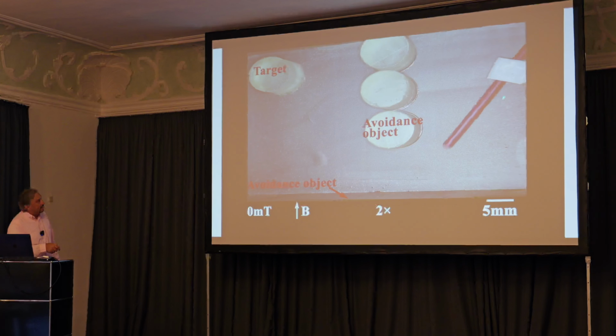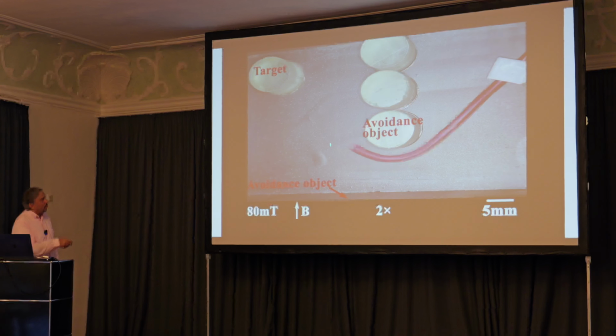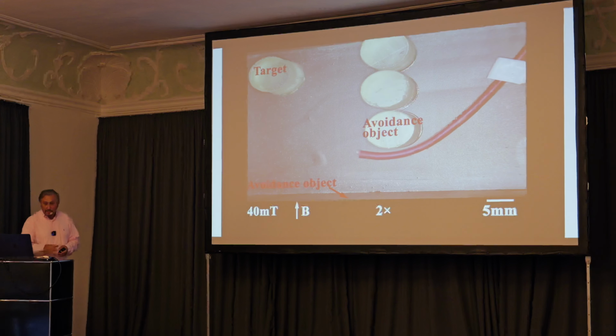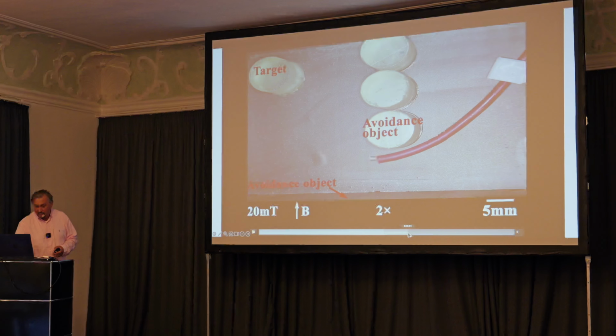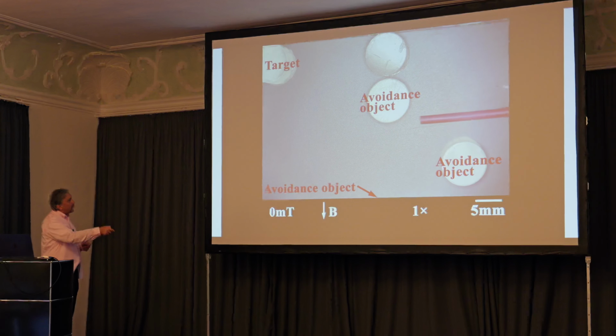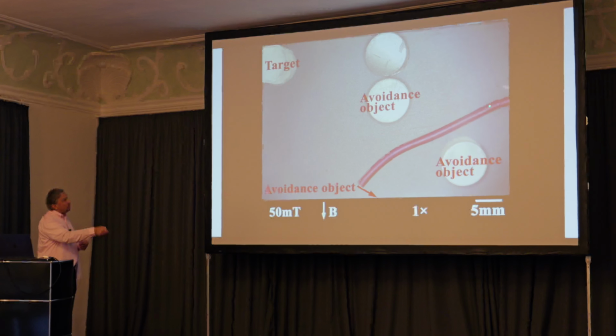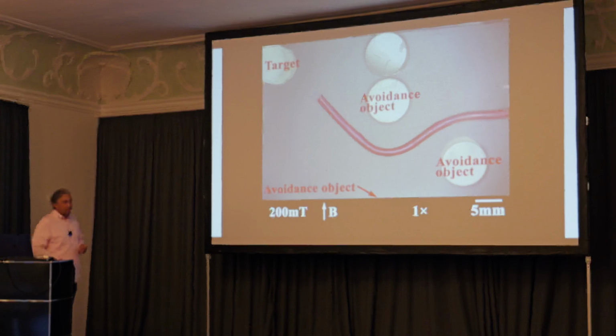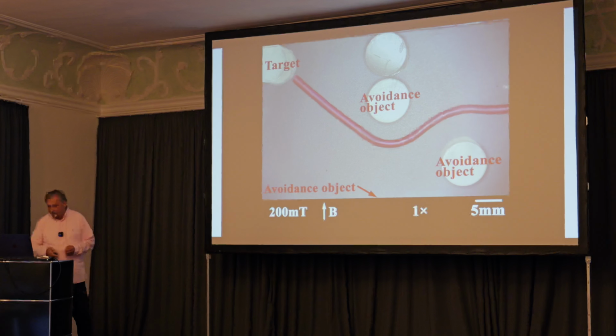But with our technique now, we can reconfigure the magnetization, and this deformation here, we can fix it, and when you align, you see that the concentric tube comes out, and we can reach this target because this deformation stays here, doesn't move with the tip, because of this new technology that we developed. And we can do the same thing with not one-point bending, but for example, for more complex objects to avoid, rather than one bending mode, you can have two fixed bending modes, as you see here, and then you can still navigate to the target this way.